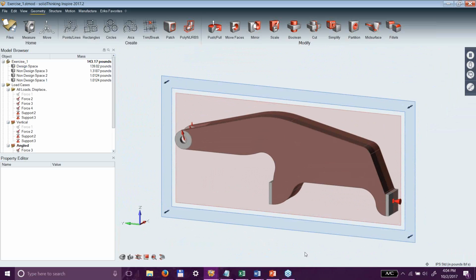The next thing that Inspire looks to make as easy as possible is the concept of units. If any of you have done analysis or optimization in a traditional sense using, say, HyperMesh or OptiStruct, units can be challenging. We have to rely on unit consistency. You need to make sure that the numbers you're putting in are in the unit scheme that you want. And if you want to change from one unit scheme to another, it requires you going in and editing every single material, every single force, the size of the part, all of that.